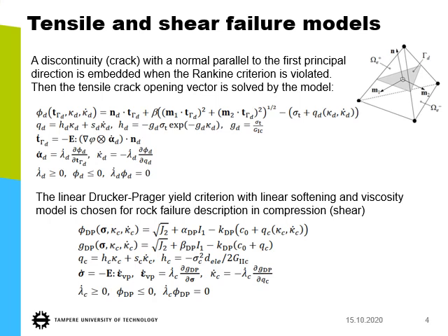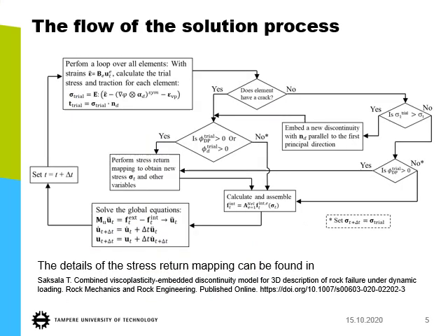And then we have the evolution equation for the stress tensor and the viscoplastic strain evolution equation defined by the plastic potential, non-associated plasticity, and the internal variable evolution model. And again, Kuhn-Tucker kind of conditions to be fulfilled. Okay, then we look at how we actually solve for this.